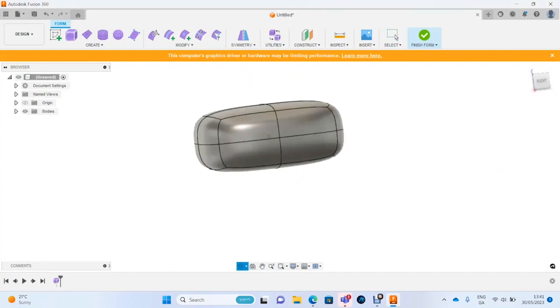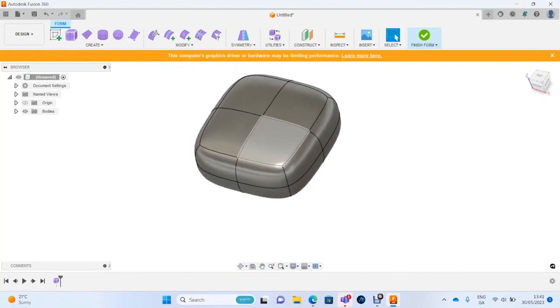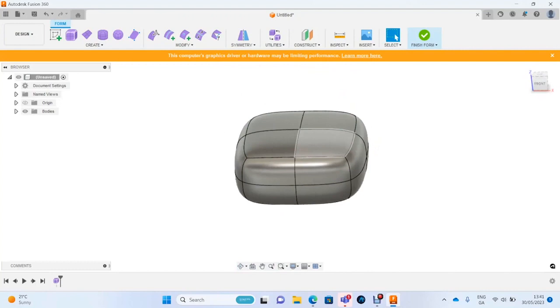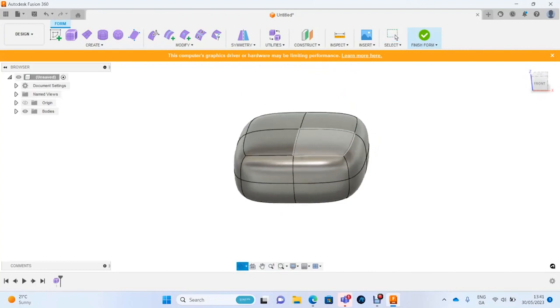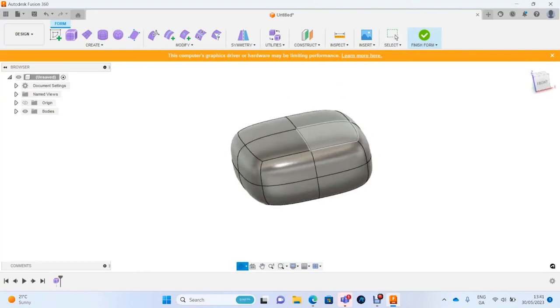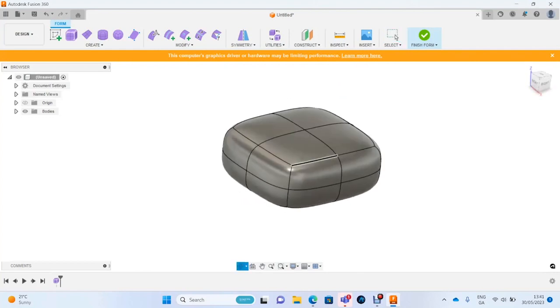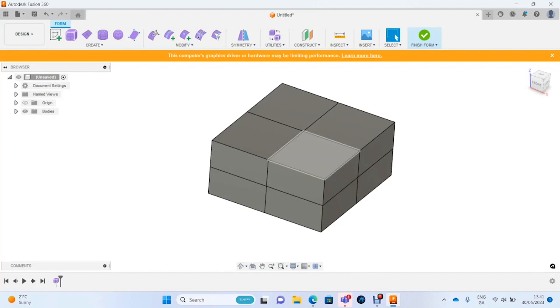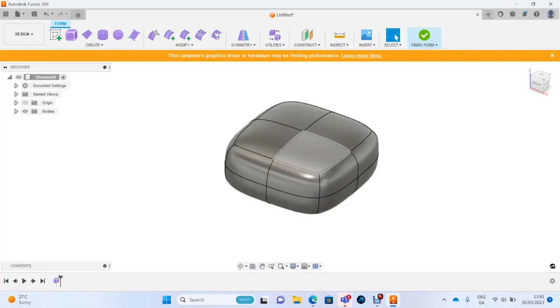So here's our basic formed rectangle, and this is currently in smooth display mode, right? It's visualizing the 3D splined faces. This is useful for seeing how your geometry is coming along, but generally when we're manipulating the geometry, we want to be working within box display mode, and we can do this by hitting Alt 1 and 3 on the keyboard, and this will just cycle between these two. Alt 1 is box display and Alt 3 is smooth display.